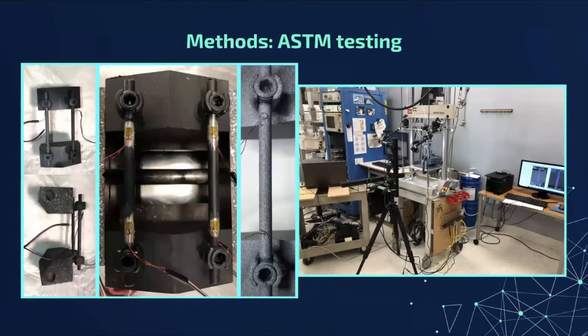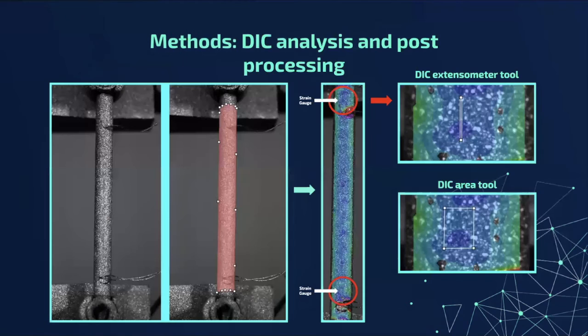To carry out testing, a physiologically relevant standardized model used to evaluate the strength and fatigue life of spinal rods, ASTM F1717, was used. Uniaxial strain gauges were placed at standardized locations on the top and bottom of each rod. Rods were then speckle coated for DIC and analyzed during flexion and extension via MTS hydraulic frame testing. DIC data was analyzed and strain distributions were generated and superimposed over the corresponding 2D images for each test.